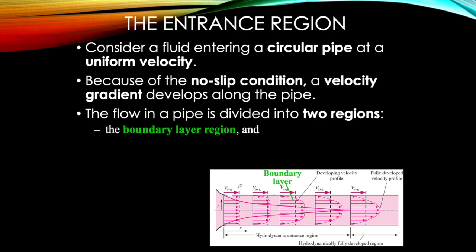So the boundary layer region is actually the effect of the viscous shearing forces caused by the fluid viscosity, because there is fluid that sticks to the pipe wall and then it will affect the adjacent layer, and this affected layer will increase as the x coordinate increases. Okay, when we combine all those layers, here is a boundary layer region.